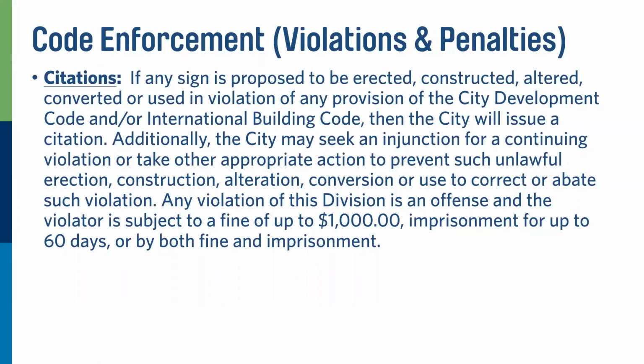They thought it was going to be CMU and they were going to use expansion anchors on it. And there's nothing there. It was stucco and wood studs. So they actually had to crawl up in the access hatch to see what was behind it and then change their design so they can attach appropriately. And I think that one was even EIFS, which is just styrofoam. So they were going to attach literally to styrofoam. So that's why we do what we do. That's why we want everything done right.